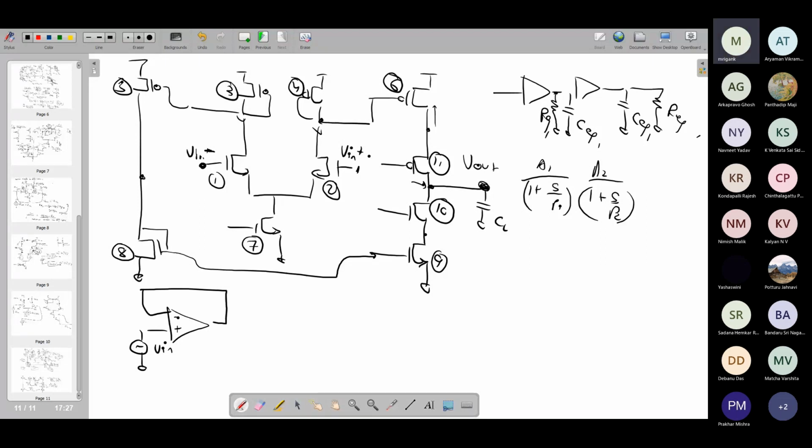How do we, in a multiple pole system, analyze the phase margin and the gain margin? So here, if you look at this kind of operational amplifier, from this point to this point, if it is a positive input, you are applying the input at the positive terminal. This point to this point, there is no phase shift, 0 degree phase shift. And then you are applying it back to the negative terminal, which is basically having 180-degree phase shift with respect to the input, which is okay. Now, at higher frequency, if we start getting additional phase shifts in the circuit, because of which this becomes closer to 180-degree, then the overall phase shift from the input point back to the negative feedback will become 360-degree.